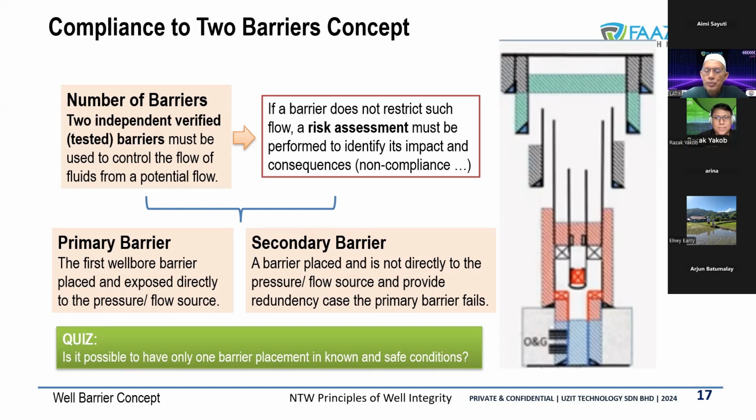And then, of course, when we perform the patch during the wireline, then we continue producing. That's the situation of a simple repair job. But if there's, for example, a puncture, a cut, or maybe the tubing is parted, of course we cannot use patching. Then the only solution is to call for a hydraulic workover unit, kill the well, pull the old tubing and rerun the completion, tie back to the old cut well. So that's how the repair job is more time consuming and expensive if it is parted.